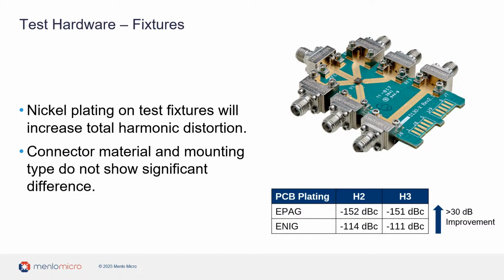We recommend using nickel-free plating such as electroless palladium with either immersion or autocatalytic gold, EPIG and EPAG respectively. Another option known to have good harmonic performance would be a silver plating.